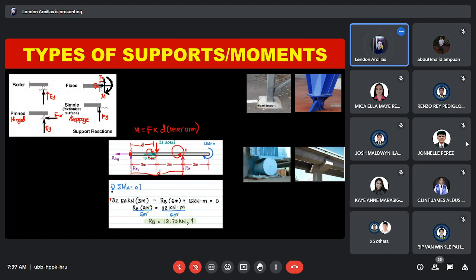So this is positive, since this is counterclockwise, positive 15, and this moment is 3 plus 3 plus 3, which is 9 meters from point A. So ay hindi pala, may ano na pala siya, may distance. Okay, so minultiply na yung force dito sa distance, so that is 15 kilonewton meter. Since yung moment dito is either kilonewton meter or newton meter, or pound force feet. Okay, so summation of all moments, makukuha natin yung reaction at point B.